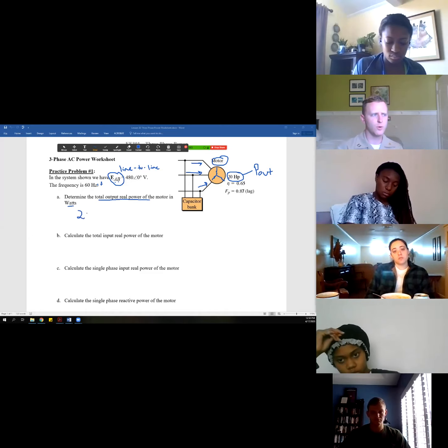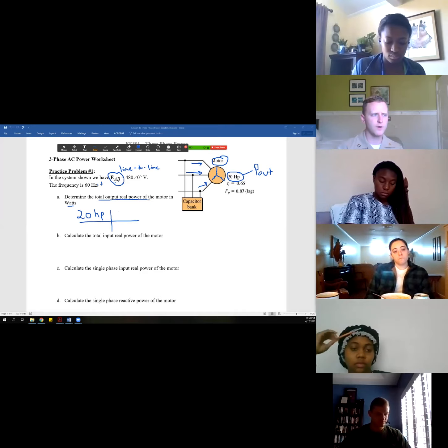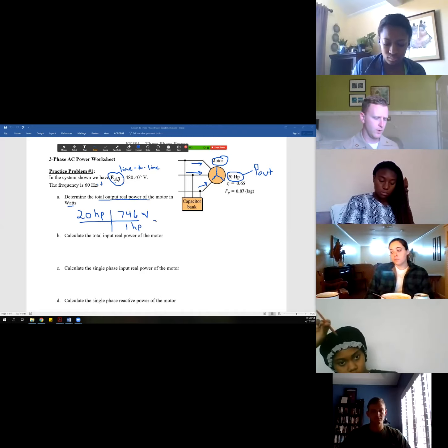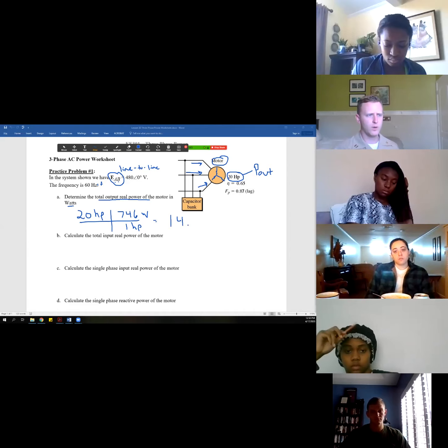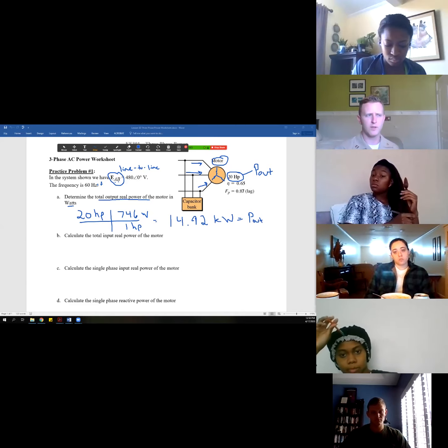So we just take that 20 HP, and we can do the railroad tracks, right? 746 watts over 1 horsepower. 746 times 20, and that gives me 14.92 kilowatts. We're still in real P power. This is still P out. All I've done right now is converted it, but you're going to need to convert it in order to use it in electricity, because everything that we're dealing in electricity is watts.